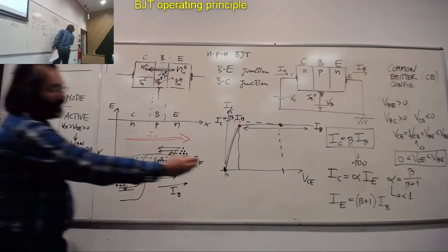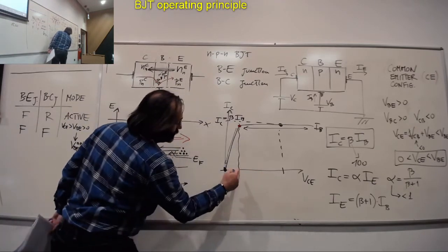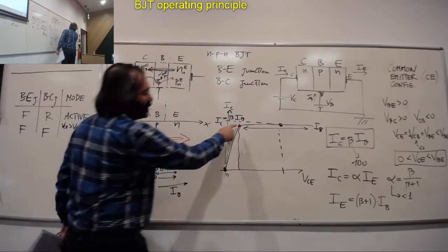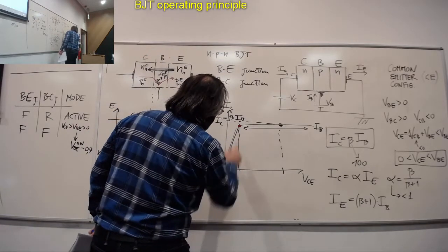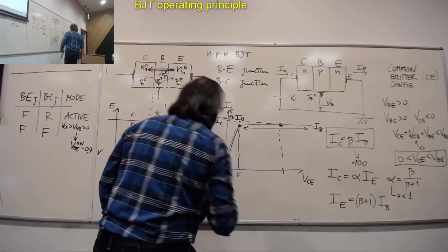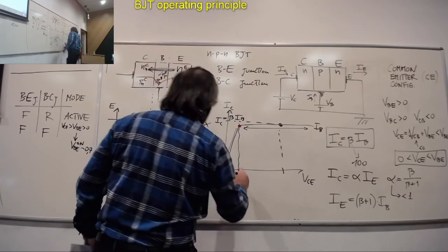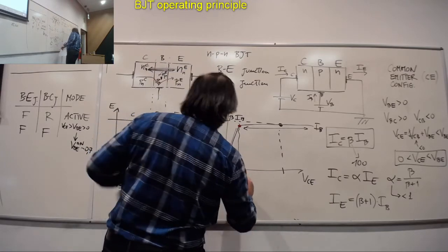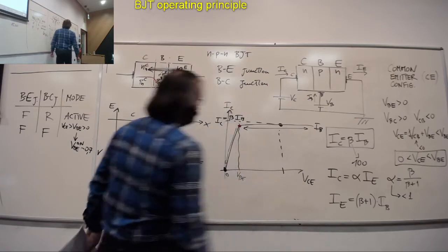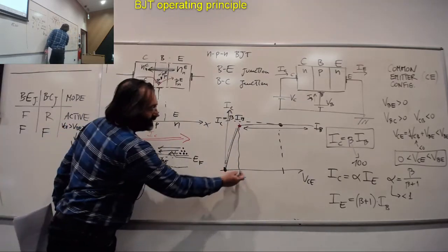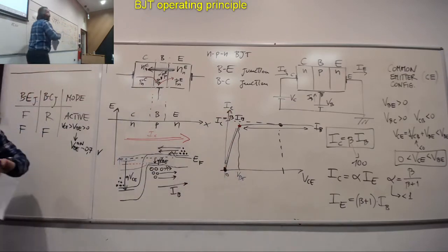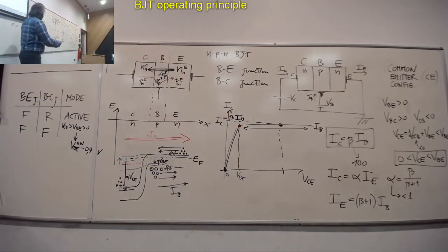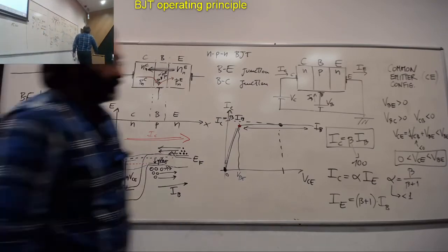As VC moves from this value here, which corresponds to, remember, VC at this point, where is the knee, VC is equal to, what did I say, VB. So between these two, the VB and 0, the current will drop dramatically now. Okay. What we have described is the saturation regime, what we call saturation.